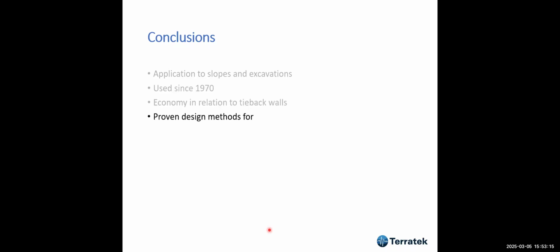And as concluding this presentation, we've seen soil nailing can be applied to slopes and excavations, used since 1970. That's the first. Economy in relation to tieback walls is about half of the cost. Proven design methods for stability, for deformation, and it's not difficult to do that.